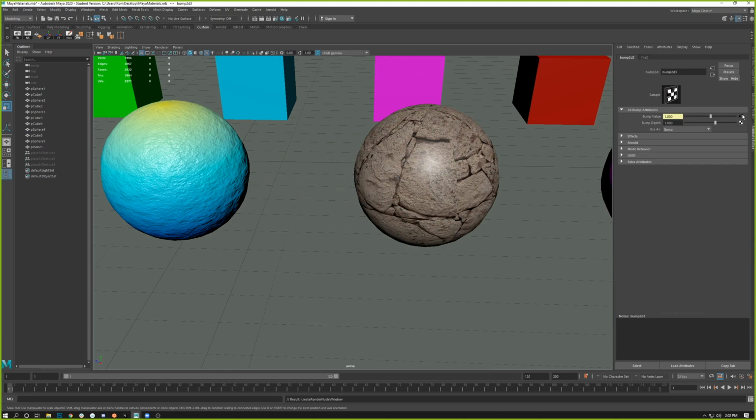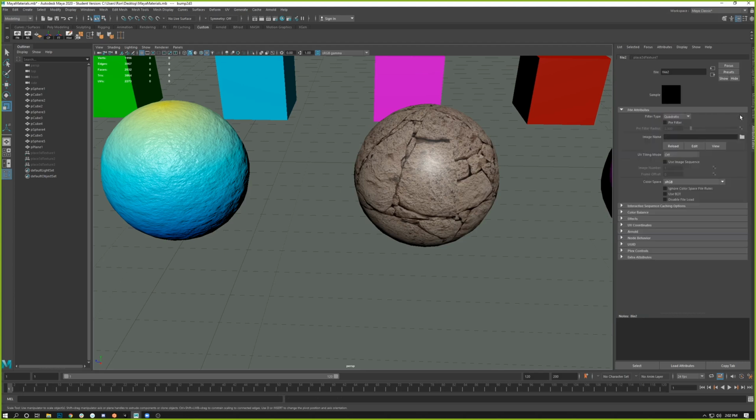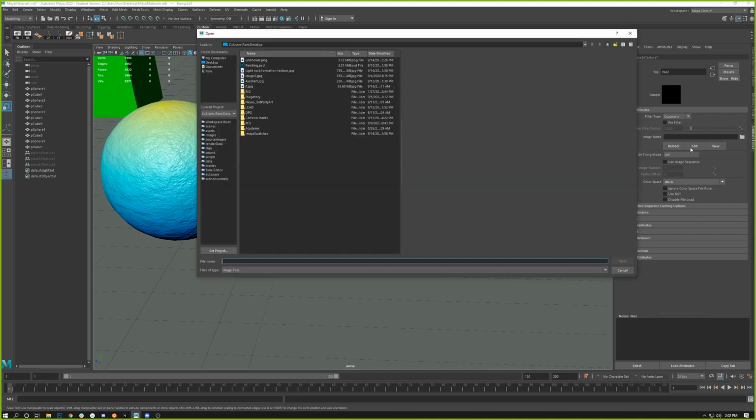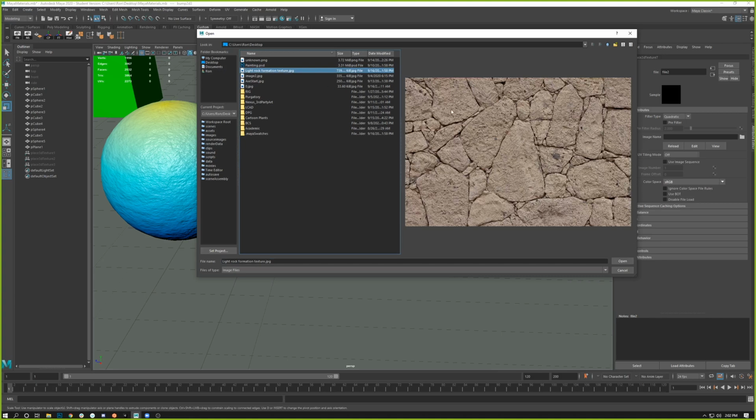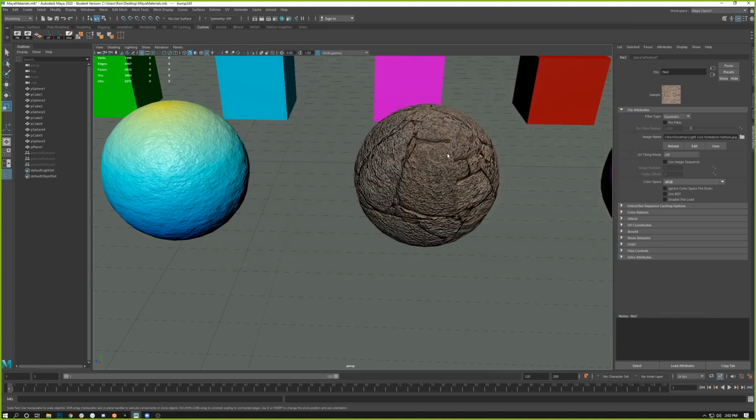The problem here is certain things like File. You can see it went straight to the bump map, but it has nothing to input yet. So that's why I did this. It's a little trickier. The value is being controlled by something else. I need to navigate to the folder icon, and I'll show this again because that takes a little bit. I'm going to go ahead and add the file on there. You can see it adds it. So where is that? Again, it's buried.